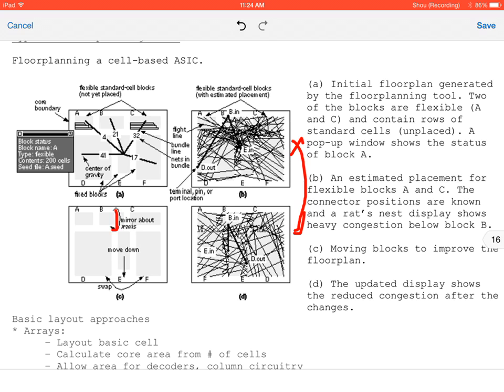We're going to go over a real brief example of generating a clock tree here. But basically, this is a really good example of how you can use the floor plan to optimize area and power consumption. These 2 circuits, B and D, do the exact same logic, but D consumes significantly less power and costs less because there are significantly fewer interconnects.